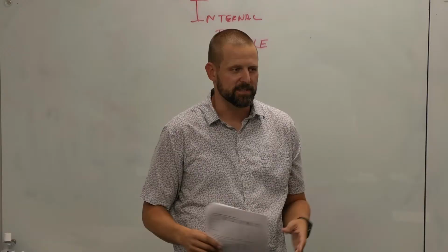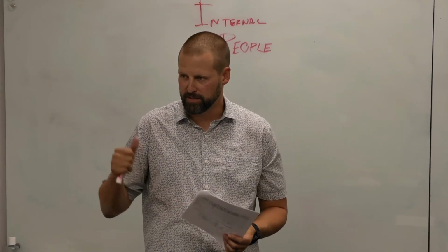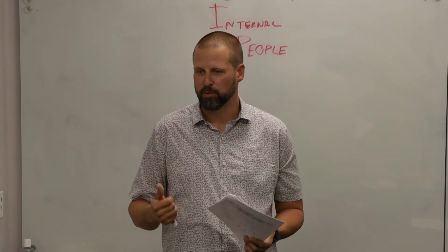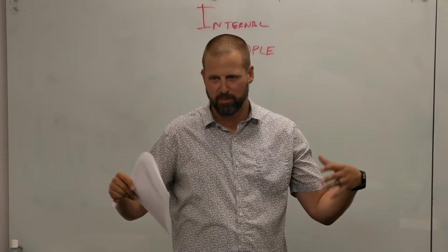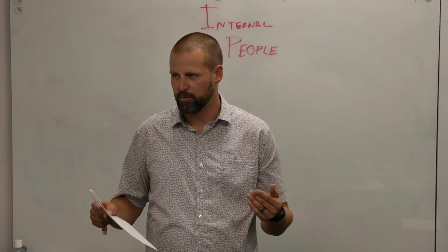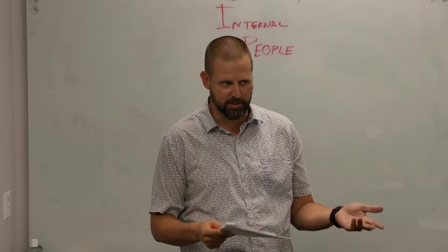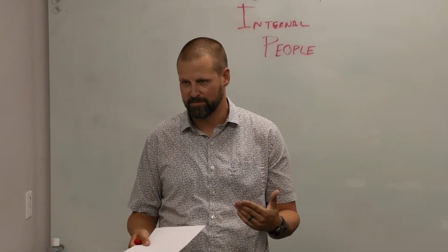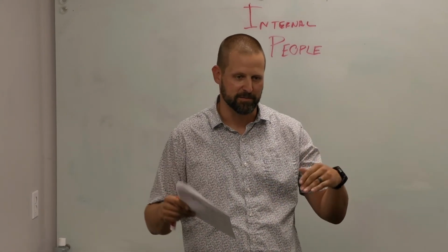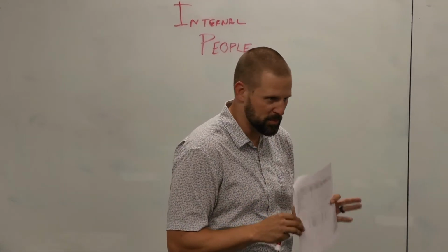There's a lot of assumptions there. At a room level, and I'm going to say this for everything, we usually are looking for a max. As we start to add up all the rooms, we're quickly going to find out we might have a floor that we're counting like 100 people, but we know only 50 people are going to be on that floor at a time. So we might take some diversity as we go to bigger components. But that's how we get through people.